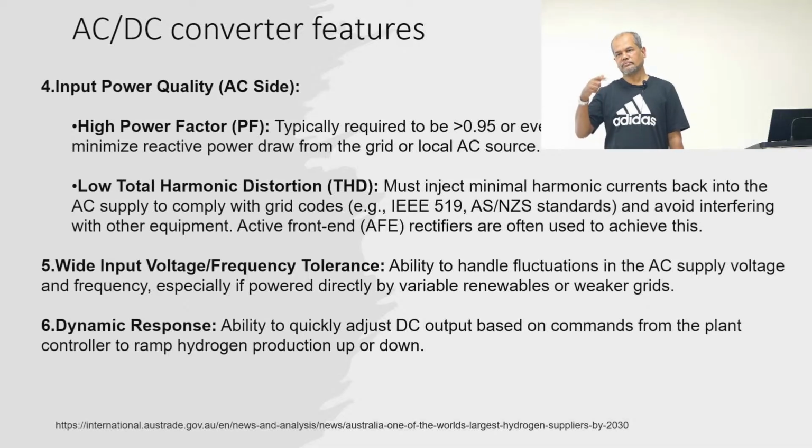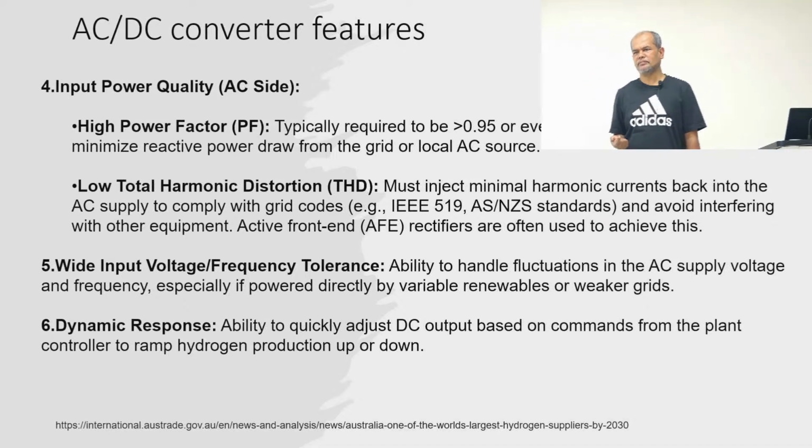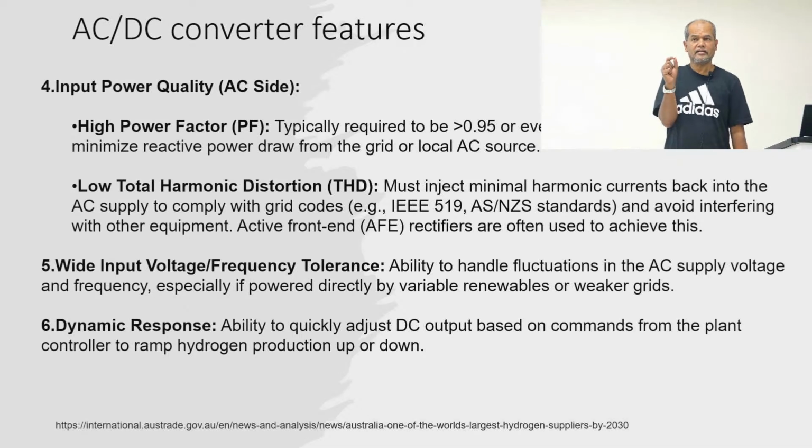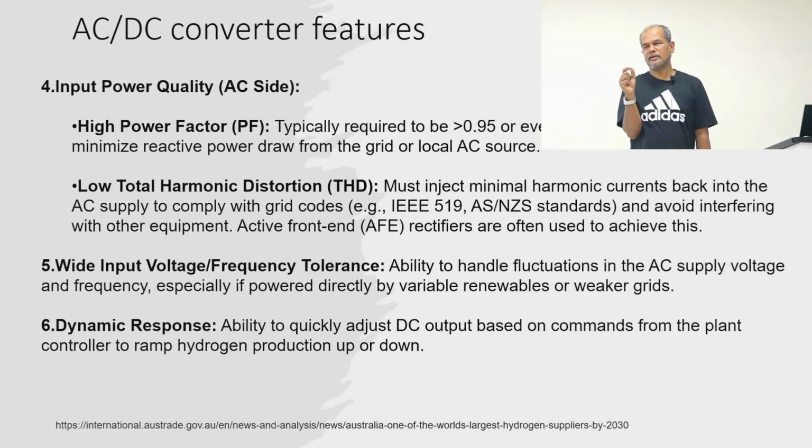Although you need to change the parameters if your conditions change, there are many algorithms you can utilize to find the exact parameters, and if you find the optimal parameters, sometimes PI works much better than very complex linear and non-linear controllers.